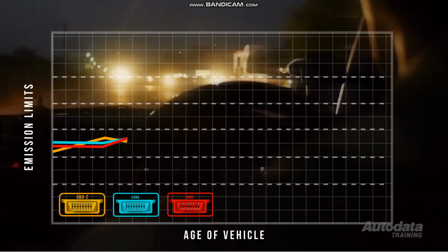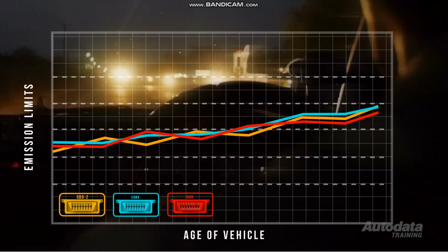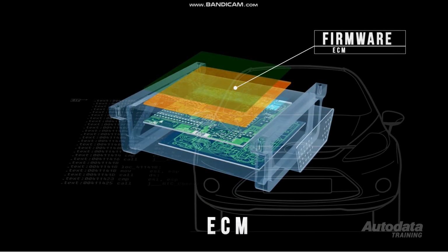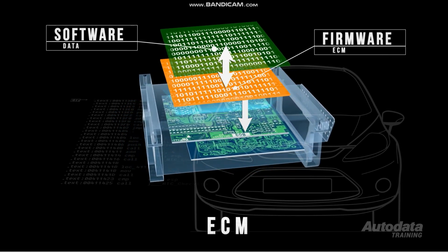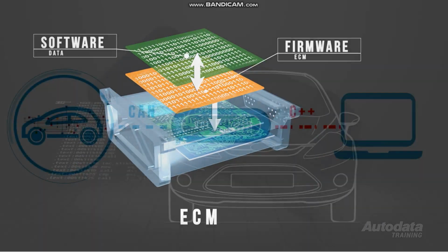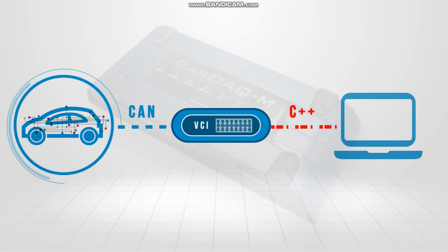When a vehicle is manufactured to meet specific OBD standards, part of the requirement is to ensure that it continues to operate and meet those standards for the usable life of the vehicle. One measure put into place that ensures that this occurs is inbuilt hardware and software security. The days of removable EEPROMs have gone. All ECMs are now a self-contained unit that can only be reprogrammed using OEM software via a dedicated portal.